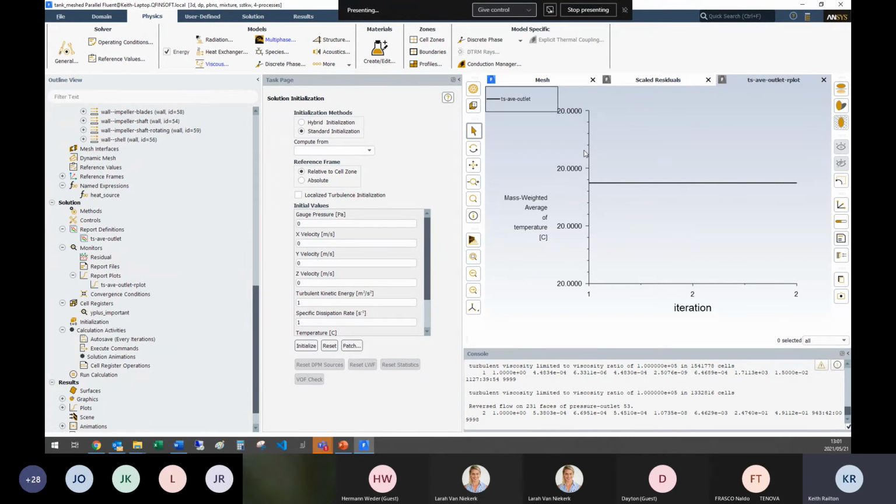So, based on simplifying it, we would rather look at a different approach. That approach is what we call the rotating region, or a frozen rotor approach, or a frame motion approach. The way that works is, instead of moving the geometry, we move the fluid in the opposite direction to what the geometry would be moving.